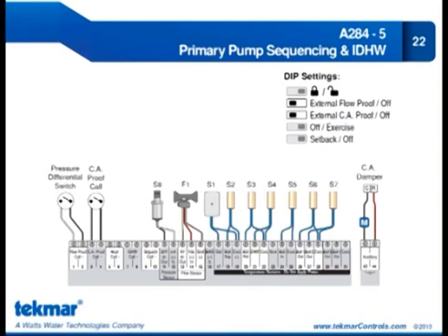So let's just say you have a half horsepower pump out in your primary loop, and you just want to use a current sensing device to prove flow. So you wire the current sensing switch into 1, 2. And you also want to do a combustion air. So you power a combustion air louver motor out of 43, 44, then you wire back the end switch from the motor into 3, 4. Okay. Yeah.